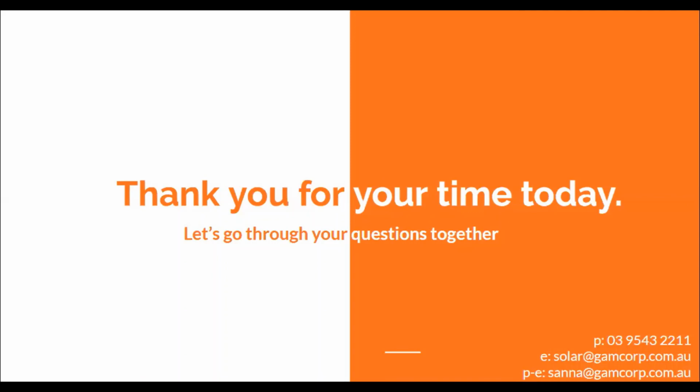But what you haven't got at all in those general certificates is the whole other 50% of it, the structure itself. The structure itself has many other concerns and questions around it. If you're installing based on general certificates, that's got no tie to a structure. It's just telling you that the array frame you're using isn't going to fall apart or dislodge on that roof, which is great, but it's not answering the problem of the building. It's just answering the problem of that little L feet.